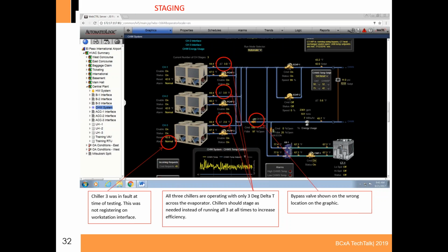If it's something that changes really fast that you don't trust, like a supply air duct static pressure loop, that's kind of a silly example, because you could just look at it during functional testing to know if it's working. You wouldn't need to trend it.